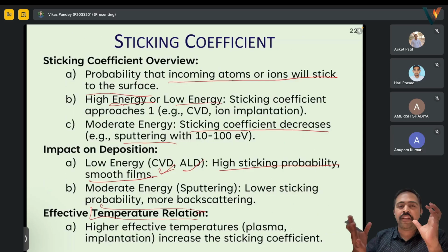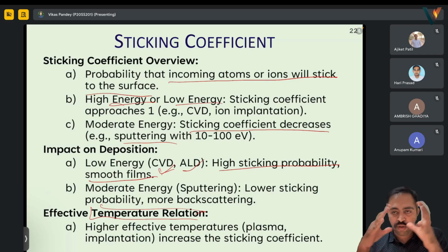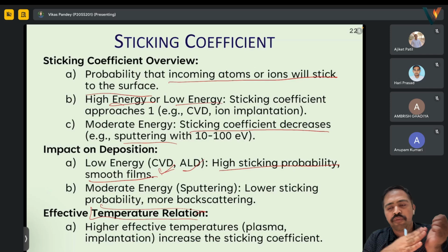So there are two types of pattern transfer: direct and indirect. We know the pattern we have on our wafer. The direct transfer has no intermediate; the pattern is created on the material itself. Indirect pattern transfer means we create the pattern on a stamp or film, like the film in the video that already had what we wanted, applied over the surface, and then that pattern was removed. We got such a pattern and use it to transfer onto the surfaces.